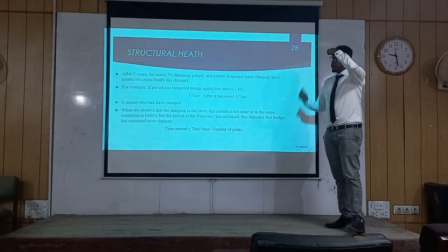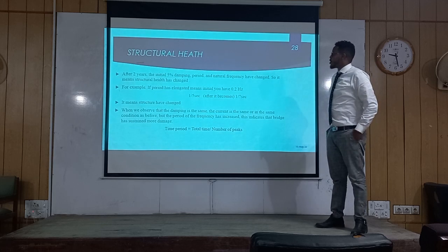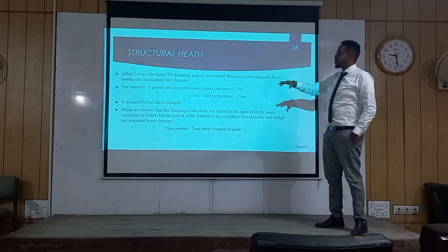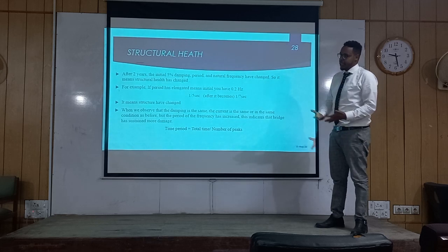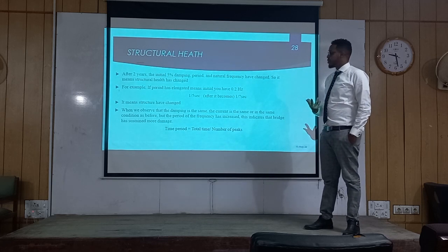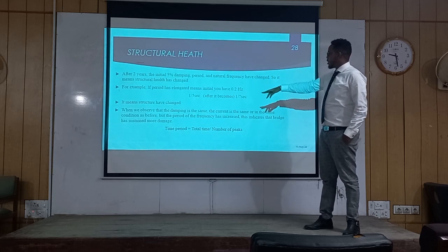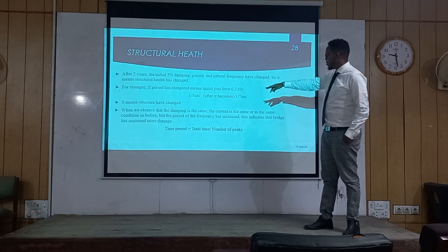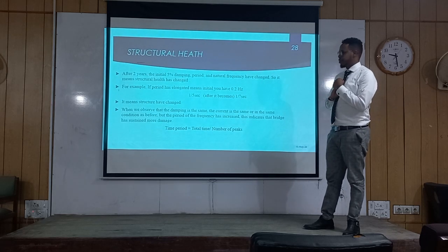The most important thing in our thesis was the structural health of the bridge. We realized that after 2 years, for example, the initial damping of that bridge has 5% damping, and the period and natural frequency change. It means if they change, then the structural health of the bridge will change. Let's say the initial period was 1.5 seconds, and after some years it comes to 1.7. It means the structure has changed. Then we have to do something about it.